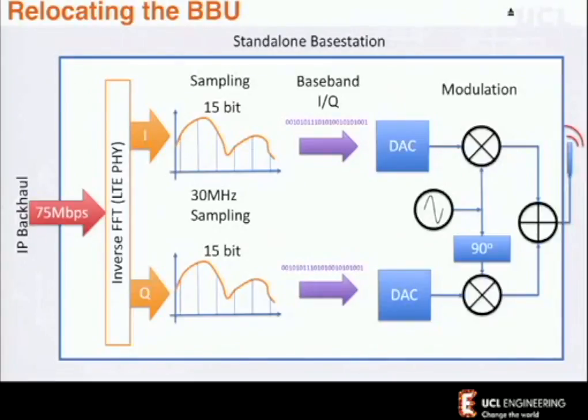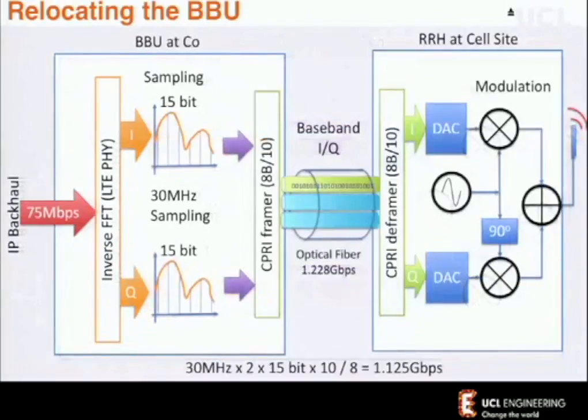So I digitize it on the uplink. To deliver it, I've modulated onto my carrier, whatever my carrier frequency is going to be, and I transmit it. If I'm going to do this digitally, I'm going to essentially break the system with this CPRI interface to frame it and send that over fiber to my remote node that just takes the digital, converts it to analog, up converts it. Probably there'll be a high power amplifier here, spit it out.